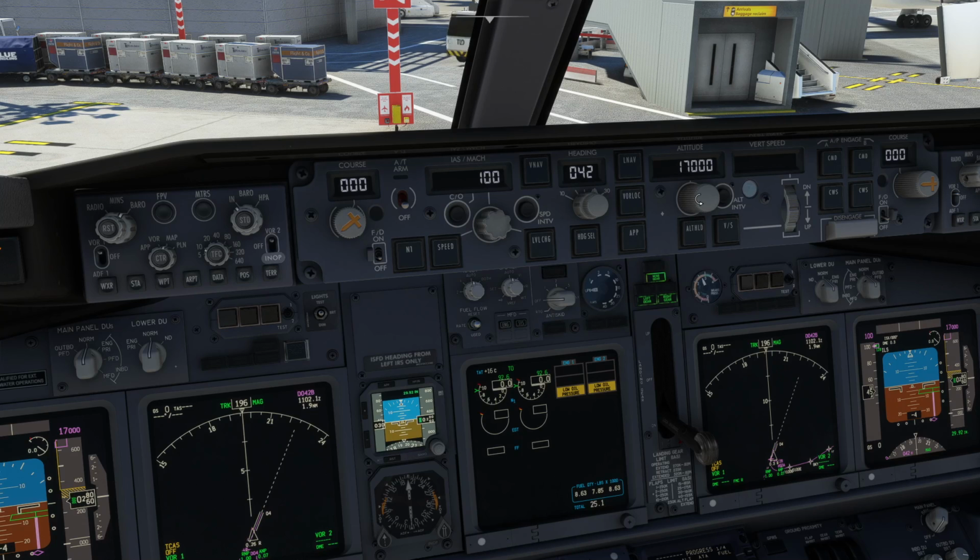Altitude, we're going to put in directly straight into our cruise altitude. So this is like simplifying it. In the real world, you wouldn't do this. You would be cleared into a step climb to a cleared altitude and then given permission to climb further during the route. But we're just going to keep this simple today, putting in our cruise altitude straight away while we're on the ground. We're going to turn on the flight directors. There are two of them, two switches. We turn them both on.